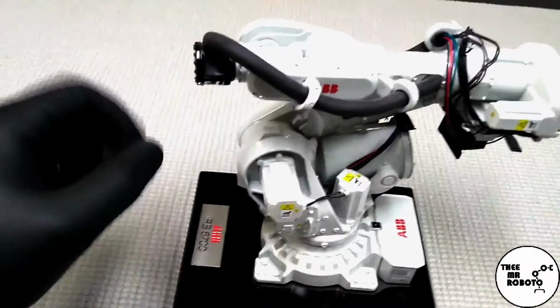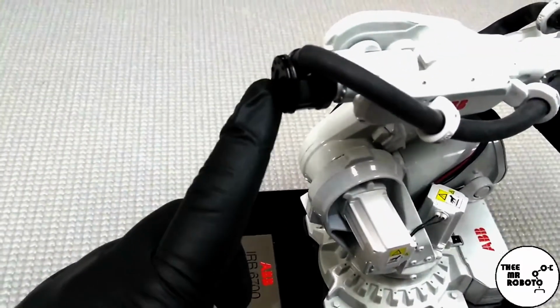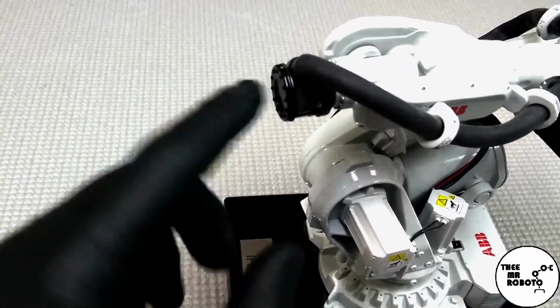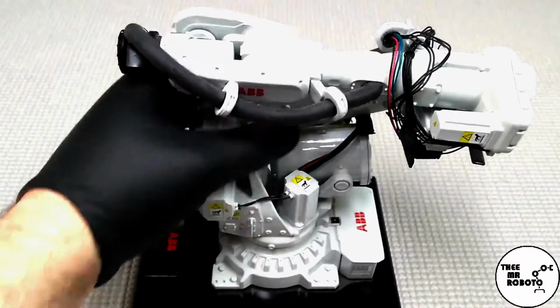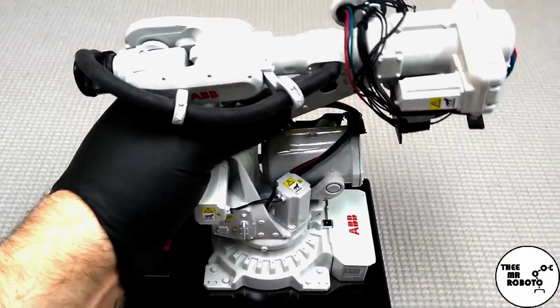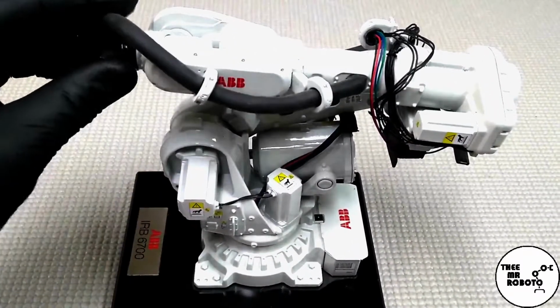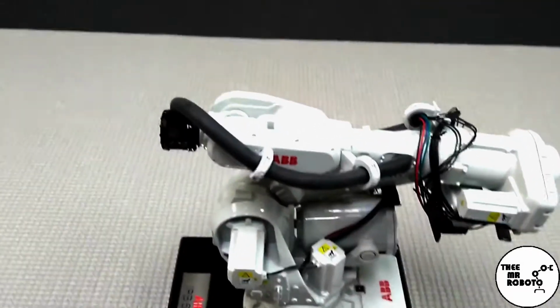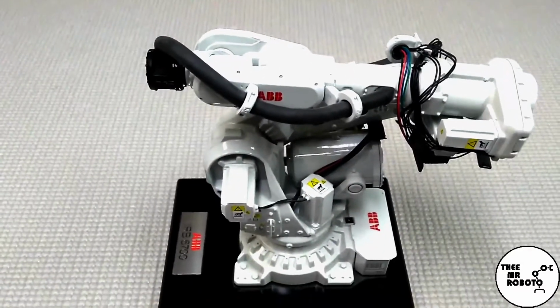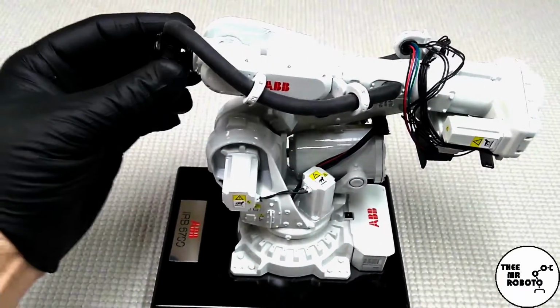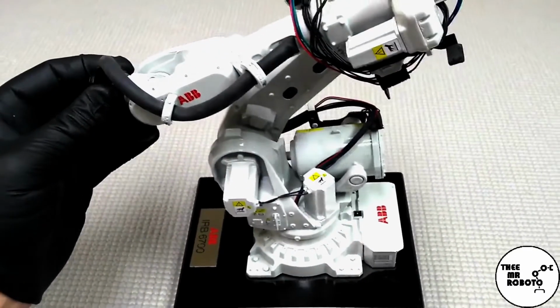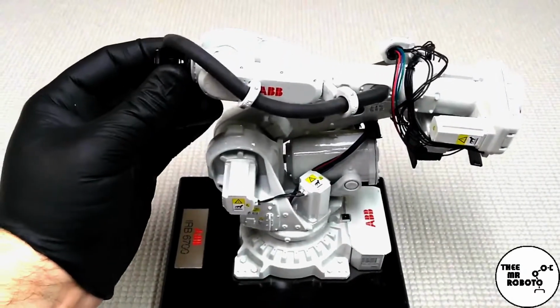And when I say moving in a straight line, I'm talking about this flange, all right? So when you have an articulated robot with revolute joints, which means that they rotate, anytime that you try and create a linear motion with a revolute joint robot, the joints all have to move in unison to create a linear move, all right?